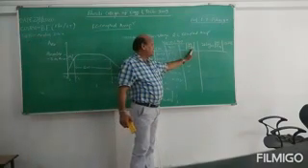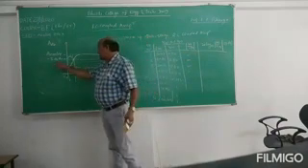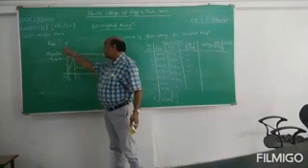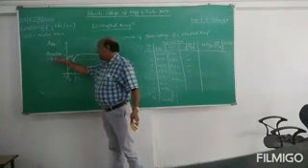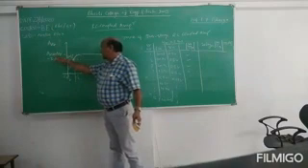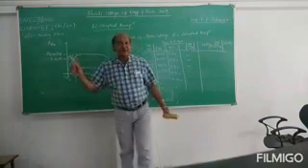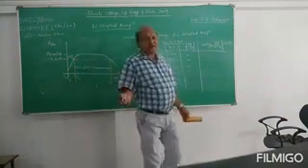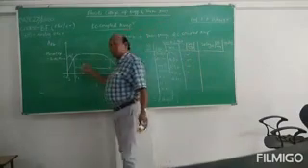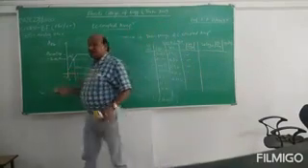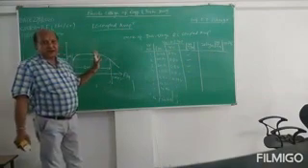Without unit, you have to multiply 0.707 times A max, and if you take decibels, you have to take 3 dB below this A max. So you will get the same thing. And the same graph you may obtain either on semi-log paper or on simple paper. On both papers you can plot it. So this is called the frequency response of the RC coupled amplifier.